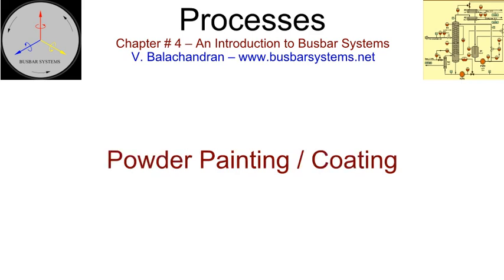Powder painting or coating. After surface preparation, the object is heated in an oven to attain a specific temperature. It is then transferred in the heated condition to a painting chamber. In the painting chamber, the object is earthed and the charged powder from an electrostatic gun is sprayed on the object, which attracts the paint, resulting in good adhesion. The paint powder is a single-component epoxy that bonds at elevated temperature. Powder that escapes the surface of the object gets collected and recycled. After coating, the object is transferred to a curing oven.